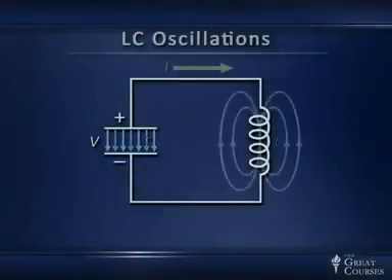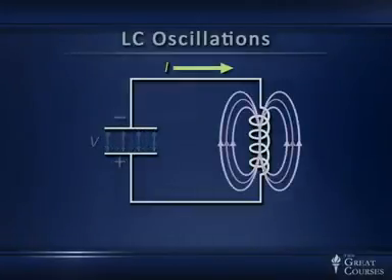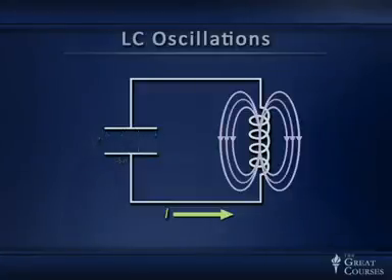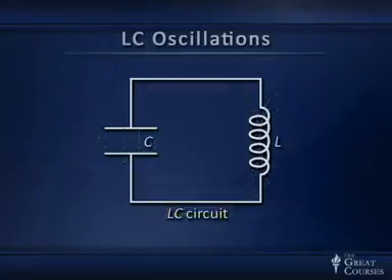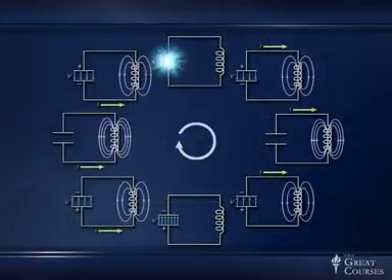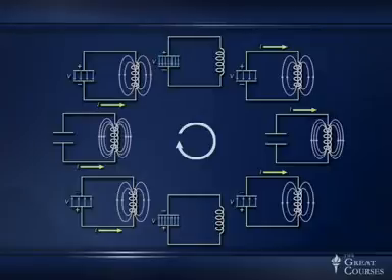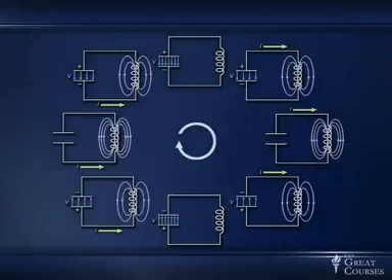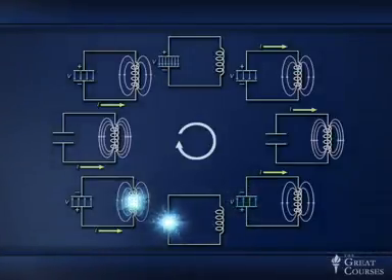We feed an LC circuit with appropriate energy at the right times because there is some loss, partly the loss we want of energy off into radio waves and partly energy lost in resistances. And you can see in this picture as you go around the cycle, you start with an electric field in the capacitor. You build up current in the inductor as the capacitor discharges. Eventually, you've got all the energy stored in the inductor as magnetic field energy, but the current can't stop abruptly, and so it goes around and around and around.